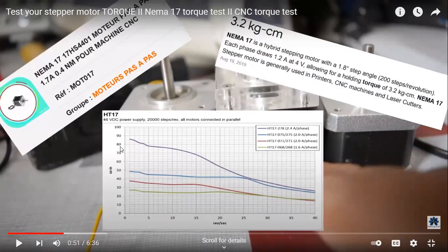This is the torque revolution graph. Each motor has a different angle of rotation. Some motors rotate at 1.8 degrees, some at 0.9 degree. It depends upon your program. If one motor is able to rotate 3.2 kg, obviously its torque is greater. If one motor is able to rotate 5 kg, then its torque is of a larger value.